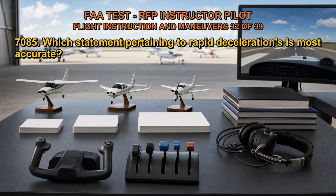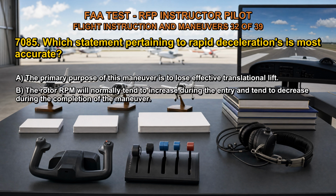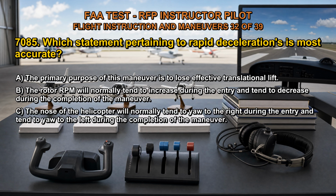7085. Which statement pertaining to rapid decelerations is most accurate? A. The primary purpose of this maneuver is to lose effective translational lift. B. The rotor RPM will normally tend to increase during the entry and tend to decrease during the completion of the maneuver. C. The nose of the helicopter will normally tend to yaw to the right during the entry and tend to yaw to the left during the completion of the maneuver.